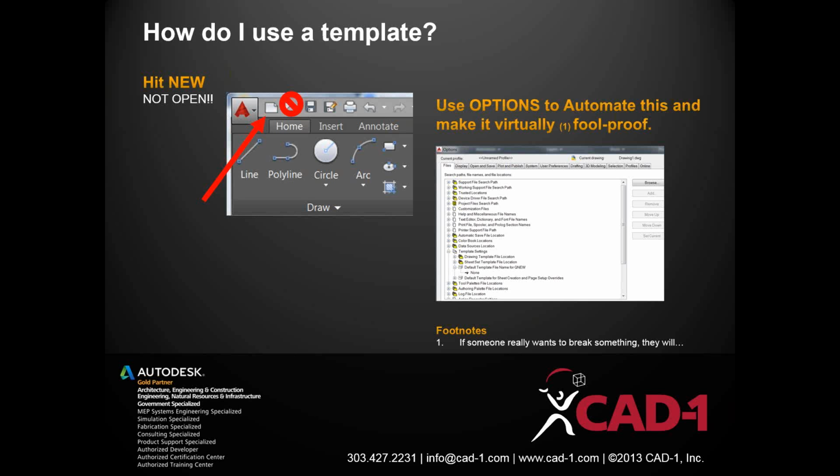You work on that. Now here's the cool thing that a lot of people don't know about: you can get in your AutoCAD options, and I'll jump in there in a minute and show you this, and you can automate the process. Right now, right out of the box, when you hit New inside of AutoCAD, the program brings up a list of all the templates that are inside the program. You can automate that. You can say, no, no, no, don't do this. I want you to use my company template. Always use my company template. So when somebody hits this button, bang, they use the company template.